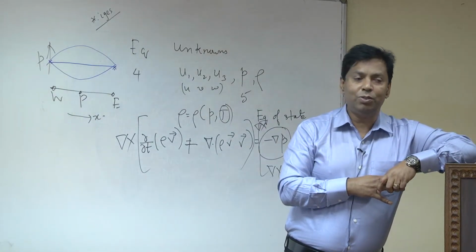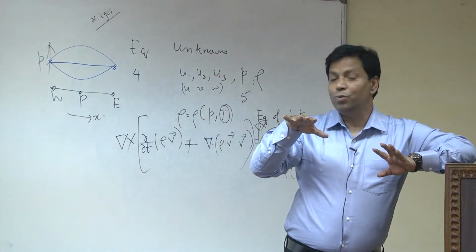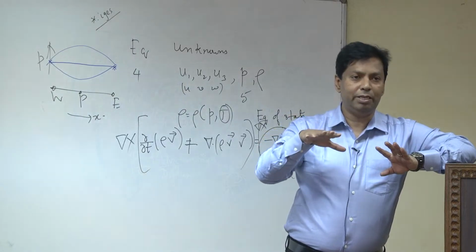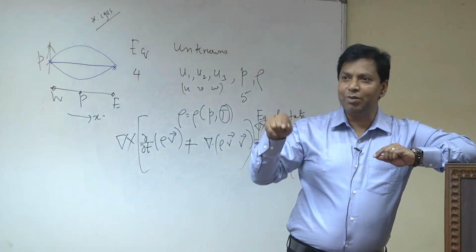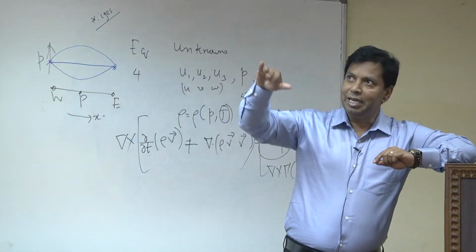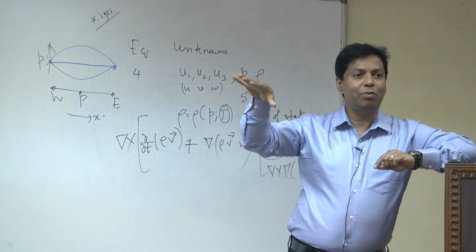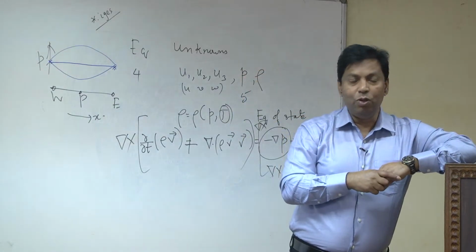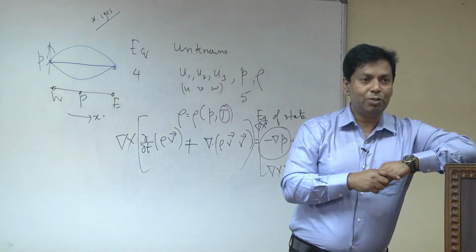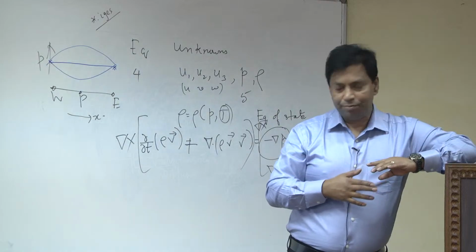So, normally what we do is validate not quantitatively, but qualitatively. We calculate something, and some people have already done it, and we found that the trends are the same. Trend-wise the same, this is the way we validate. And we do a lot of mesh dependence tests, so that our mesh or our grid is not affecting our results.